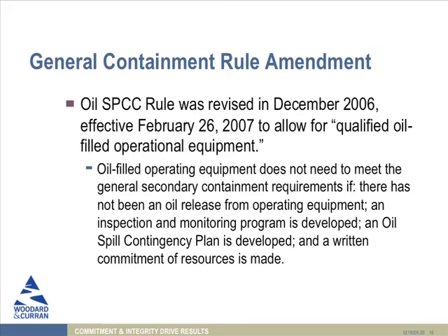You're not going to build a big dike around that because you don't want water building up around your electrical transformer. That's not a safe scenario. So there's limited things you can do. Now, say your transformer was on a pad and then it's surrounded by a dike and it's filled with crushed stone. That's a good general secondary containment measure, because any oil that's released from that is very likely going to be seeping right into the ground and not traveling very far because of that crushed stone around there. So in most cases, that's going to be sufficient. But where you've got that one on the slab and then the drain right there, any oil is just going to run right to it. So it's really hard to do anything with that.